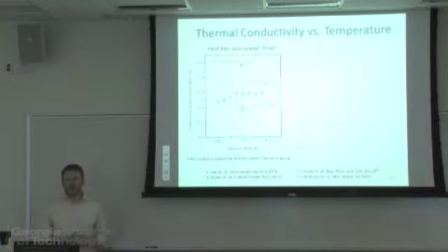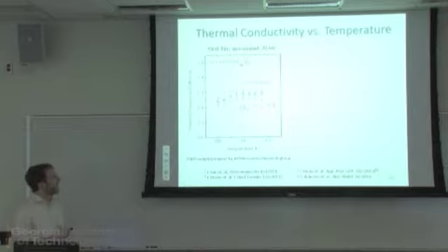In my most recent work, I've been looking at polymer thin films and TDTR. First we just started with some P3HT. Jeff Hernandez has been making some spin-coated films for me. We want to look at this because it's one of the most common systems measured for thermal conductivity, although there aren't that many temperature-dependent measurements. So our measurements are here. At room temperature there's really a plateau in thermal conductivity.